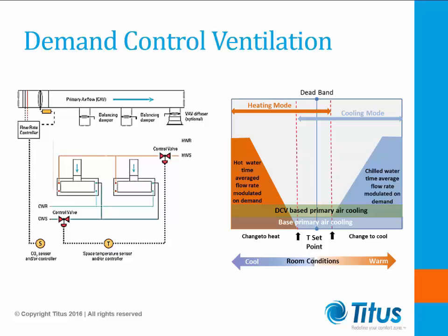Although the beam's primary airflow rate may vary as the damper opens, the CO2 sensor should adjust the primary space airflow rate according to the volume of CO2 that it's sensing in the space. In this application, the beams are designed to deliver the design cooling capacity of the space at a primary airflow rate that coincides with the average occupancy of the room.